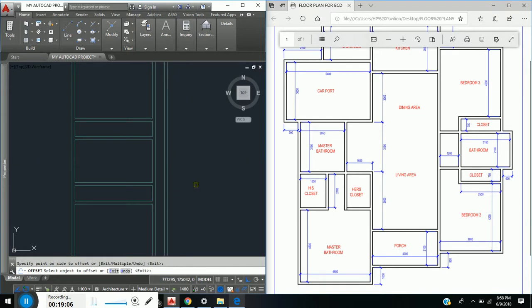Now, that wall that was just offset must be terminated with this wall somewhere here. Likewise, it should be terminated with this wall somewhere here, so as to have these two termination points, because that's where this wall is supposed to be. To do that, we do a fillet.